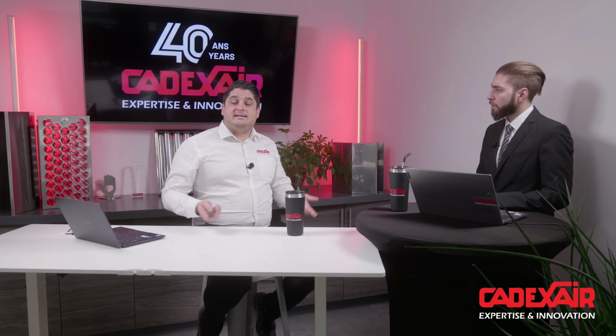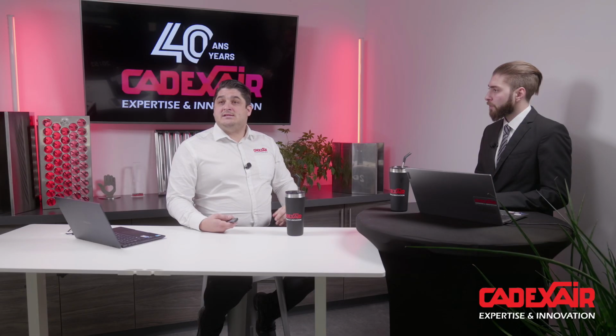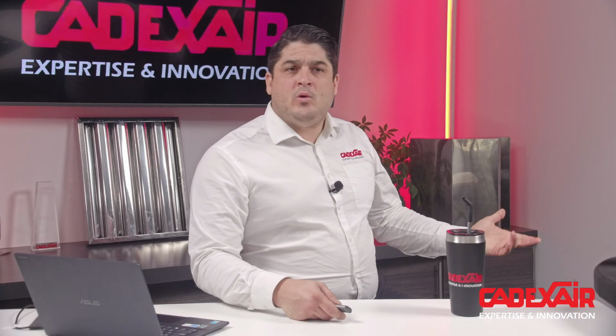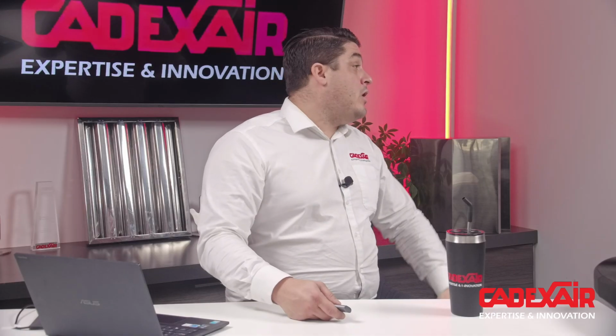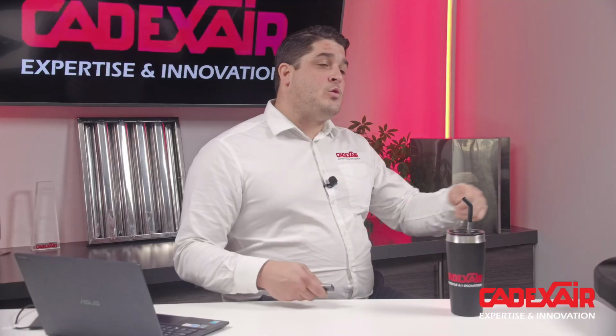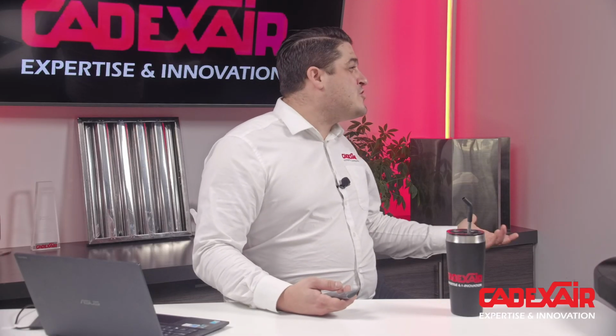When you have a long duct run, you prefer to keep the grease inside the hood rather than having to remove it down the ductwork. Cleaning ductwork is not that easy. At Cadexair, we have over 10 teams doing hood cleaning almost every night. So you need to open access doors, spray the grease, scrape it. It's not that easy. It's not a magical robot.